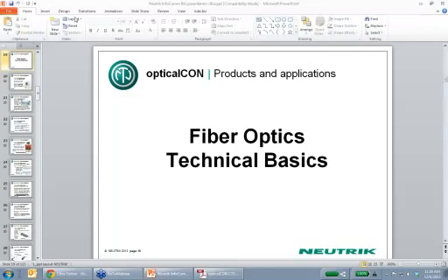Yeah, let me talk about that. It's a really important point. We don't want you to over-specify fiber. It's not in your interest or your client's interest. Cat 5 and Cat 6 are great solutions. Multi-core snakes are great solutions. A reason I bring up these distance limitations is I want to help you understand where you do need to move to fiber and where you don't. Our point here is not use fiber everywhere. Our point here is use fiber when it's appropriate.